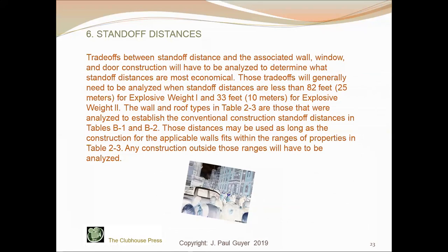Okay, so standoff distances. How far away from a facility do you want to keep aggressors? And usually, the biggest consideration probably is vehicular standoff distances, because the vehicles can carry the greater explosive weight. Okay, let's see now.